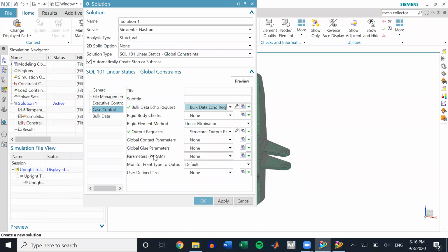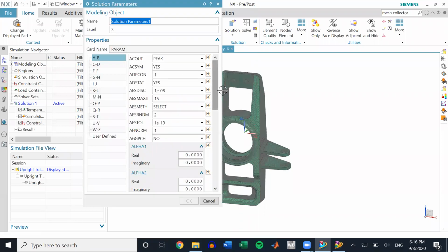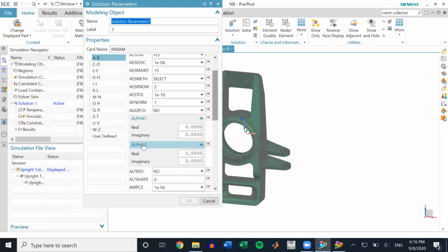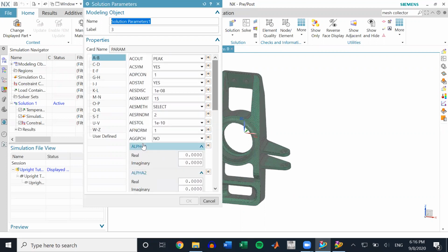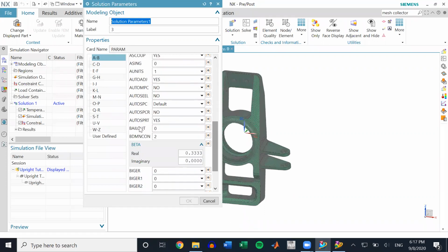And then you see parameters right here. You can go into this menu with the button next to parameters, and there's a bunch of different settings that you can play around with. I'll show you two that I was able to learn recently. First one is bailout. And what this does is basically force solves your simulation if it's set to -1.